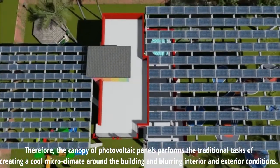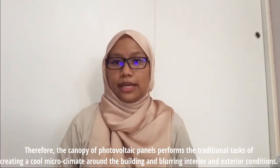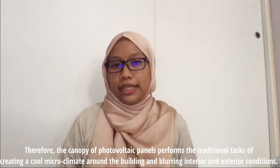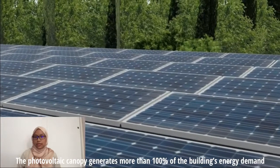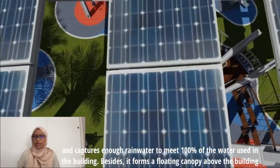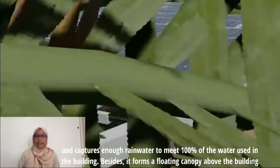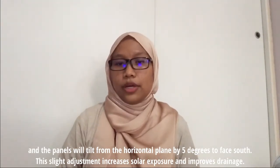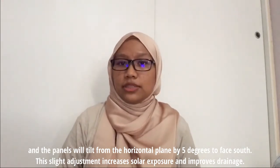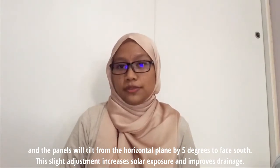Therefore, the canopy of photovoltaic panels performs the traditional task of creating a cool microclimate around the building and blurring interior and exterior conditions. The photovoltaic canopy generates more than 100% of the building's energy demand and captures enough rainwater to meet 100% of the water use in the building. Besides, it forms a floating canopy above the building and the panels will tilt from the horizontal plane by 5 degrees to face south. This slight adjustment increases solar exposure and improves drainage.